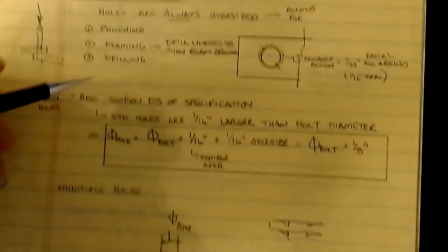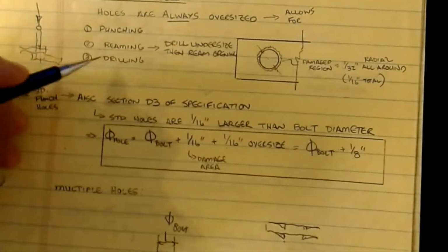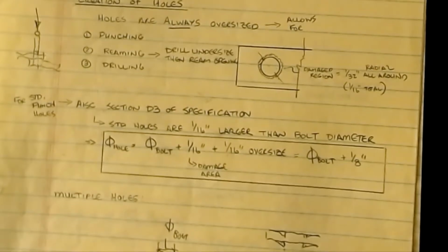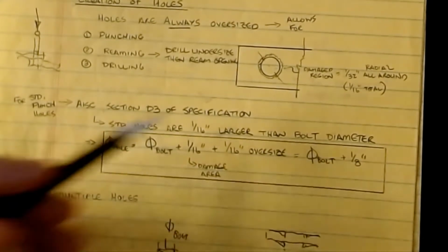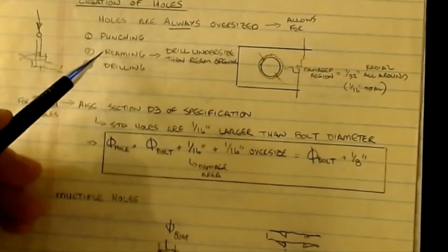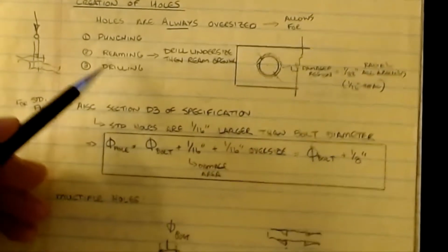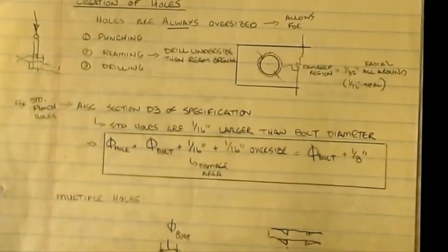So that's drilling, and then reaming is a combination of the two. I drill a small hole, and then I shove another piece inside that reams it out and makes the hole wider. That's generally a little kinder than a straight punch, but again it's labor intensive because now you have to do two rounds of drilling, although they're probably a little faster than trying to do a big single hole drill on those.